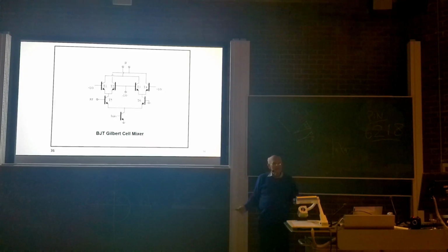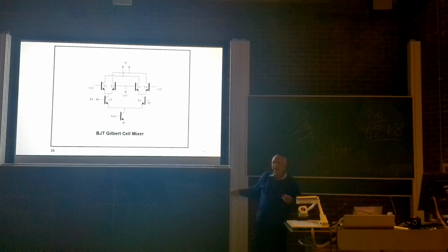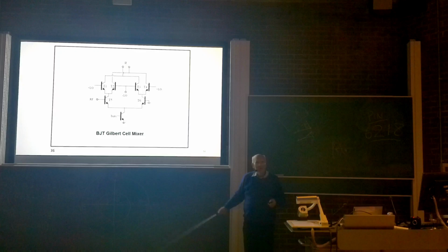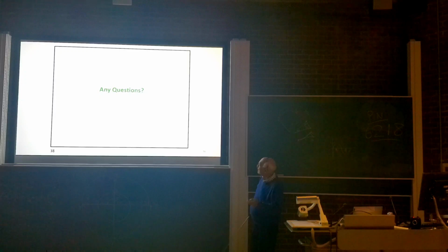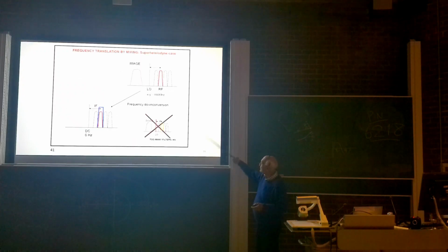The really neat thing about it, and particularly done in high RF, is that there are no capacitors here, none at all. And in fact, you can make arrays of these things with no capacitors. So you can actually get rid of one of the big problems. And I'm going to skip through this and show you what I mean in a moment. These are the receive side.